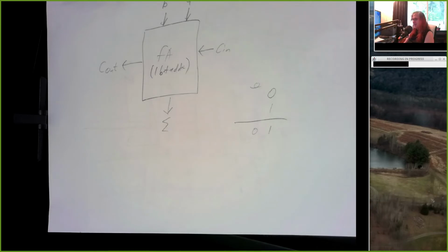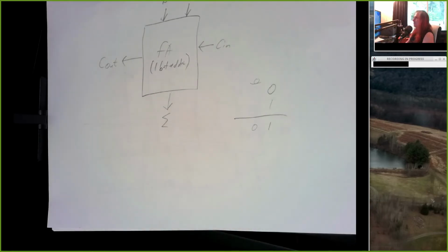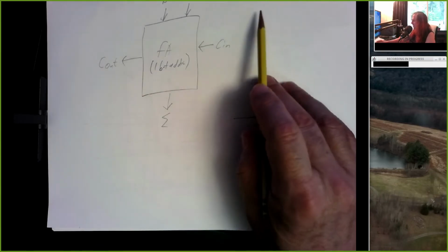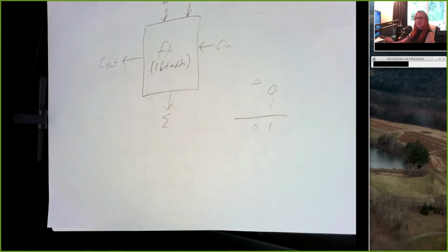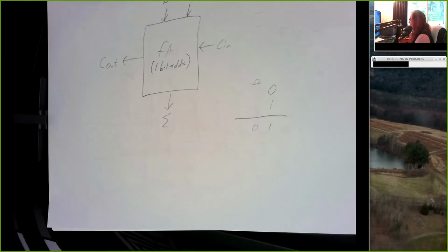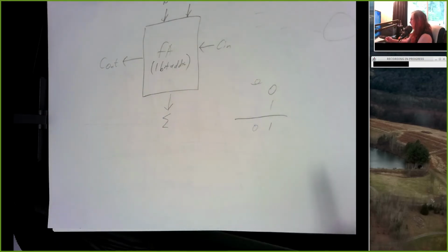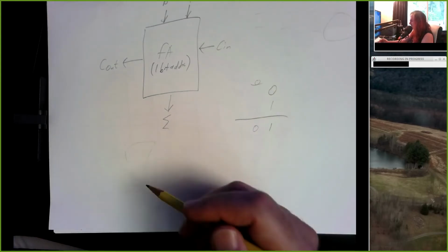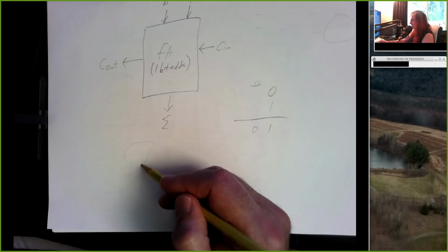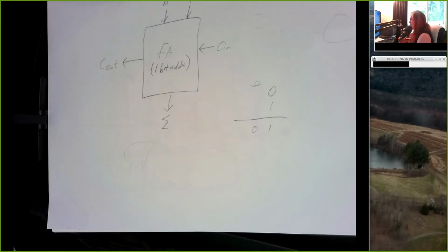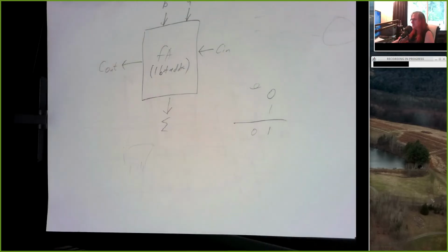And then if something's not working at the end, you can look at your schematic and say, oh, I forgot to put this line in here, right? You can highlight the power connections in your component ID block as you make those. You can use the column that says no connection, and if you see that this chip has 3 pins that aren't connected, well, look at that chip in Tinkercad. If there's 4 pins that aren't connected, you missed a connection somewhere, or made a mistake in the schematic, right? So the schematic really works well for wiring the circuit up in Tinkercad.